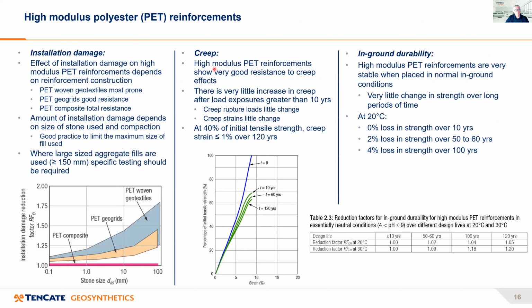Now, I'll contain my talk here to just high modulus polyester reinforcements. It's the area I'm most familiar with. And I'm going to talk about the effect of installation damage, look at the effect of creep, and we'll look at the effect of this in-ground durability. So let's turn first to installation damage.